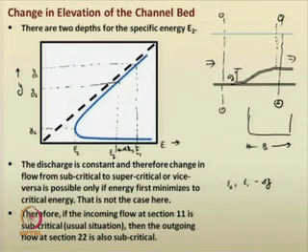This Y2 can be above the water surface, or below, or the same; we do not know. Based on the exact numerical values, you have to identify it. So, you select the corresponding subcritical depth Y2. That is how you determine the downstream flow depth.